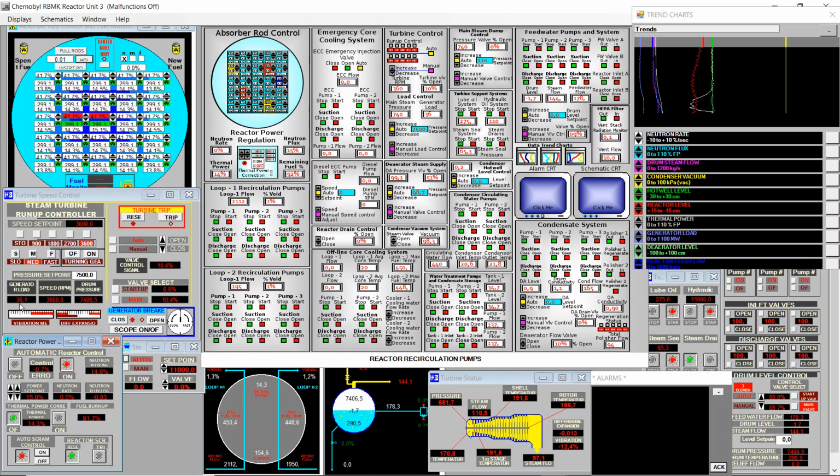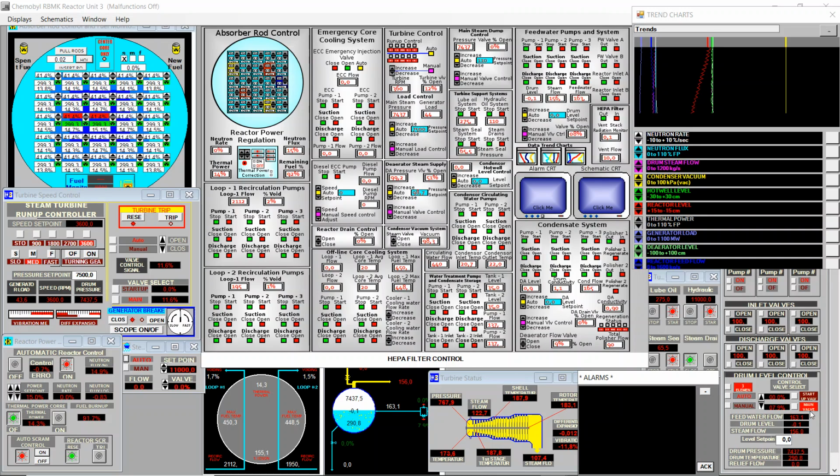Okay, this looks like it's stabilizing at 36 megawatts, power set point 15, and the feed water pumps are set for a power higher than 80 megawatts, which is 3 pumps, 3 element control here, and main valve. So we can start switching things to feed a power below 80 megawatts.